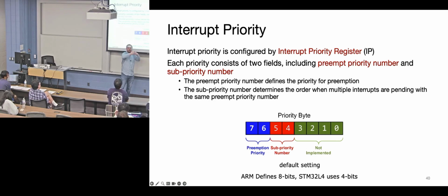And so it says, okay, I'm in an interrupt. Say my priority is 5, and I have a whole bunch of other 5s. This is the next 5 that should be serviced next. Then I believe it's whatever's next in the queue. I don't know exactly how they make that last little tiebreaker. Yeah, maybe the NVIC decides as it goes up the table which one's the lowest value. That's an interesting question.